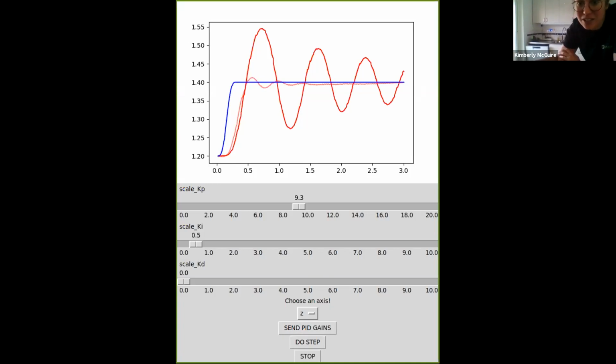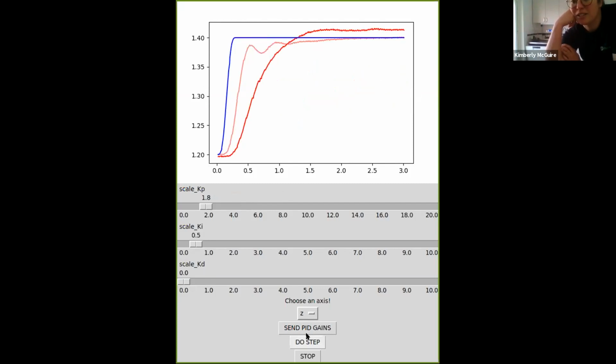Let's see, there is also, why is there a 0.2 second delay before the position starts reacting? Very good question. So this script didn't exist before I started working on it. I'm just saying that the attitude controller and the attitude rate controller are not tuned properly. So those gains are still too small. Even though I tuned it a bit, I would say a P gain of 4 and a D gain of 1 was already pretty good. So that was already quite quick. And if I would put back all those gains, then you go to the old one, which is pretty slow. So that's why I'm motivated to also make scripts for the attitude and the attitude rate controller, which are not tuned properly yet.